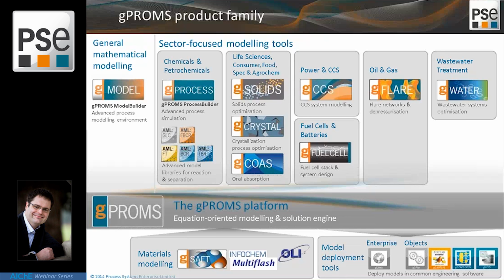So what we do is you can specify your boundary condition, and maybe I should point out one thing to be absolutely clear. We chemical engineers tend to associate boundary conditions with those for the independent domains other than time, whereas mathematicians consider boundary conditions or initial conditions, what we consider to be only for time, to be a subset of boundary conditions. To clarify that, I will speak in initial conditions, meaning a boundary condition for time, but it's always at the initial boundary, so that's why it's an initial condition. And I will talk about boundary conditions when it's everything but time.